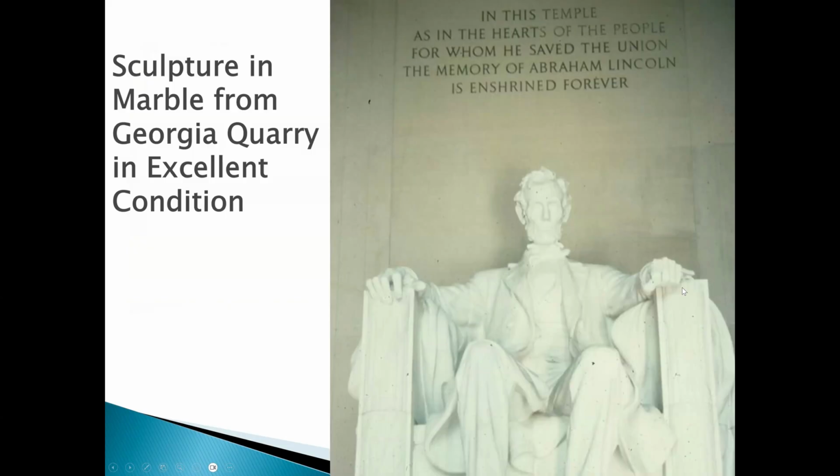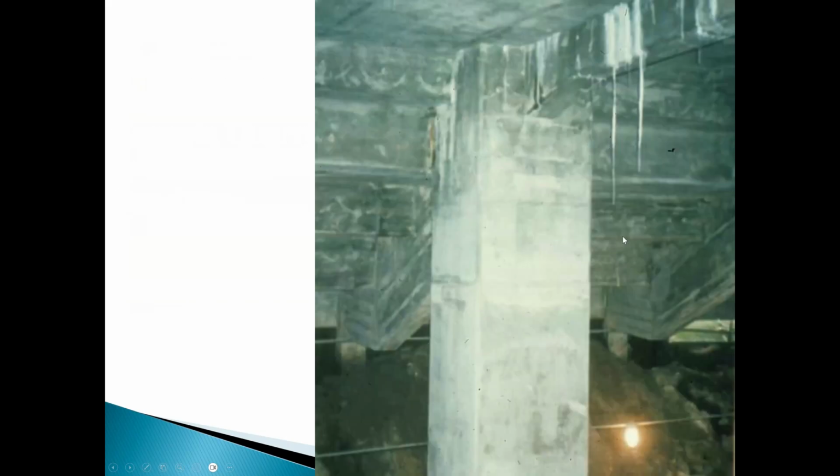But outside the building, to help the tourists, they clean those steps all the time. There's a lot of de-icing salts used that was infiltrating and going down and causing corrosion of the massive concrete substructure that supports the weight of the marble of the Lincoln and Jefferson memorials. And it's really massive under the Lincoln. This shows some of that concrete substructure. You can see the stairs. You can see the stalactites. Water's coming through cracks. Stalactites are forming from both the de-icing salts and the lime leaching out of the concrete, et cetera, and forming stalactites.